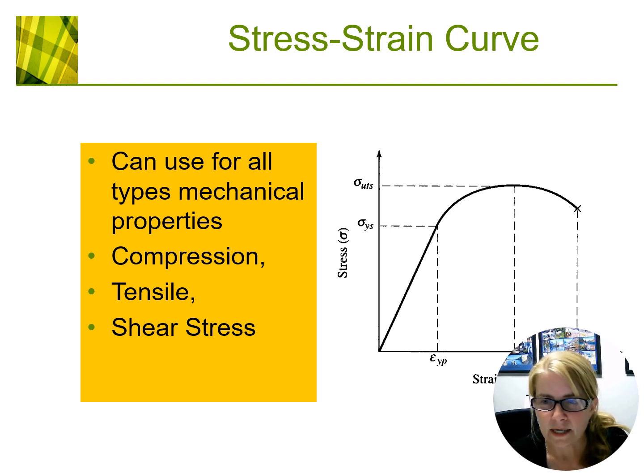This one at the very end over here is ultimate strength. So the very last line going up, straight above my head right there, is the ultimate strength. The ultimate strength is the point where the material busts. The ultimate compressive strength, the ultimate tensile strength, the ultimate shear strength is that very end. After that it breaks and it's no longer useful at all.